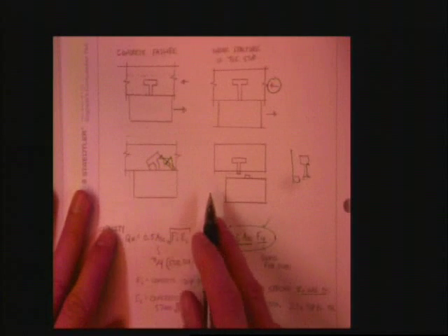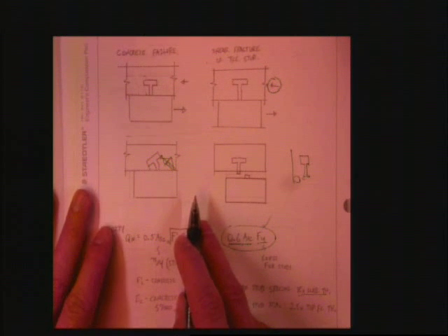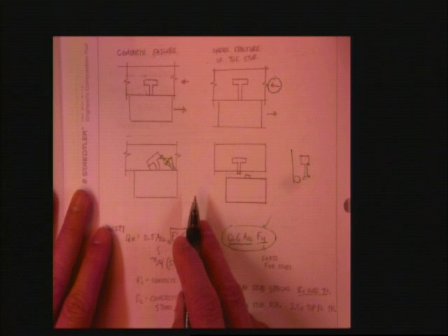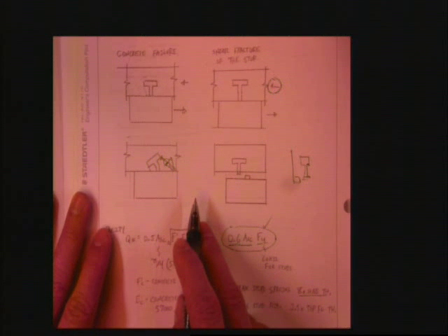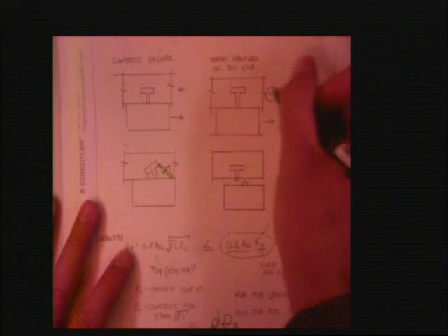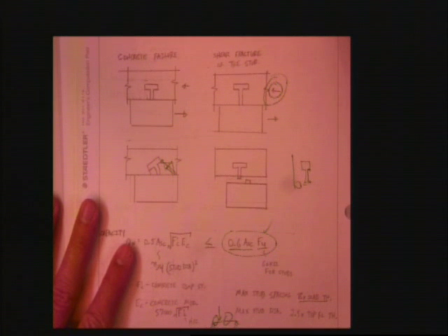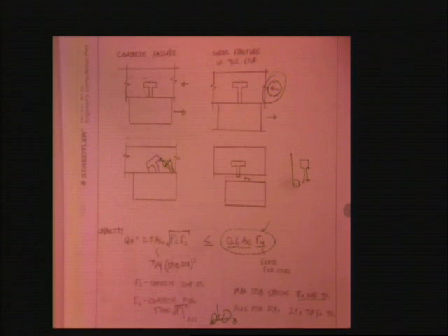When it comes to design of studs, how do we do that? That's right. The load divided by the capacity of the stud. How do I get the load? It's from all the load in the concrete, right? All the load in the concrete. That's the short answer. Okay? Now, when you go and design those studs, you're going to get a certain number you need. Where do they go?